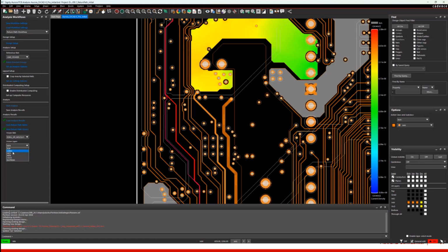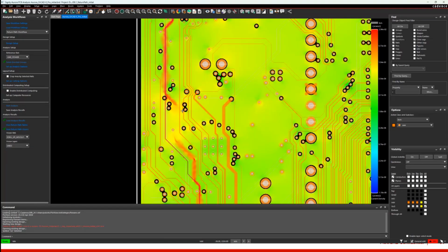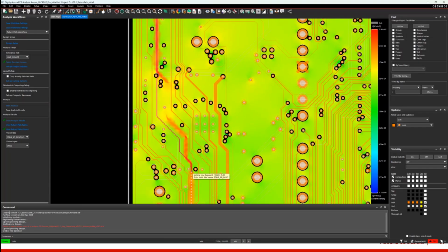If there's nothing in R3, okay, here we have something that means we go from layer 5 to inner 3, and we can see here ground on layer 2. There's a big way where the current goes. So you see, in some cases, the current goes through your complete design, and you never know exactly which vias can be used or will be used, and that makes it so difficult to say beforehand where you should go.